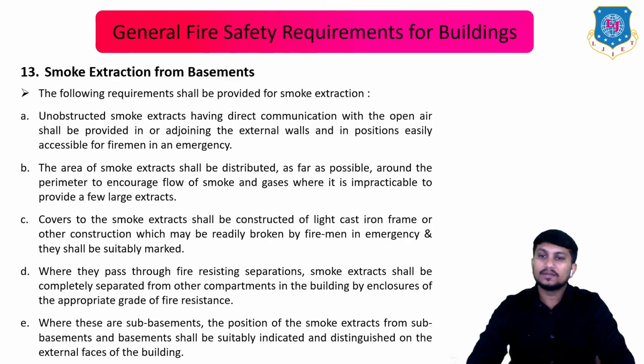Okay. Wherever they pass through fire-resisting separations, smoke extracts shall be completely separated from other compartments in the building by enclosures of the appropriate grade of fire resistance. Where these are sub-basements, the position of smoke extracts from sub-basements and basements shall be suitably indicated and distributed on the external faces of the building. Okay, that's all about the various fire safety requirements for the buildings.